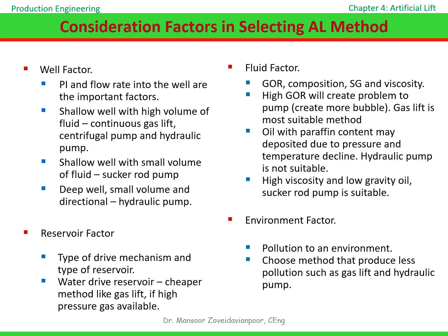Next are the reservoir factors. We need to understand the reservoir drive mechanism and the overall reservoir condition. For example, if a water drive reservoir has access to high-pressure gas, gas lift can become a very attractive and cost-effective option. The third group is the fluid factors. Fluid properties often drive the final decision. High GOR fluids create challenges for many pumping systems because gas interference reduces pump efficiency.